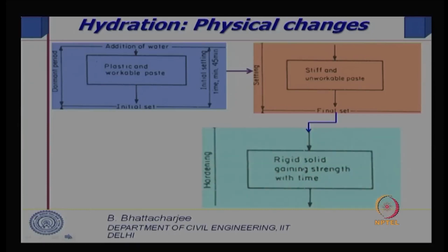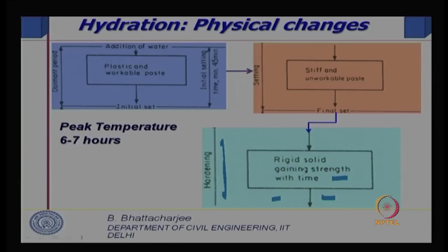Followed by them is rigid solid gaining strength with time, and this process we call as hardening. So, it will gradually gain strength, it will become now hard. The solid was soft initially, not very strong, but with time it will gain strength and will become stronger. That process we call as hardening. So, these are the physical changes in case of hydration.